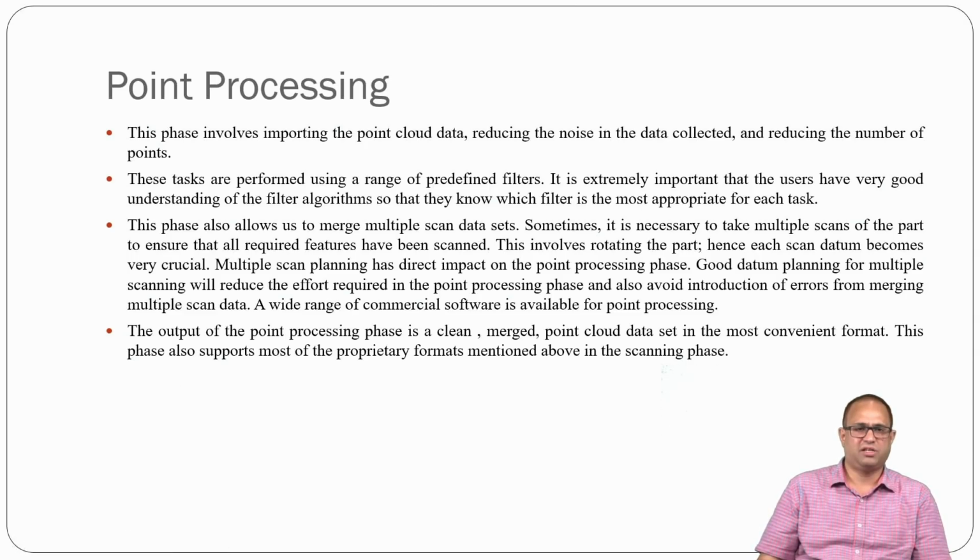This point processing phase involves importing of point cloud data, and how to reduce the noise data which is collected, and reducing the number of points. Especially these options are performed using a wide range of predefined filters. So it is extremely important that users have a very good understanding of the filter algorithms.